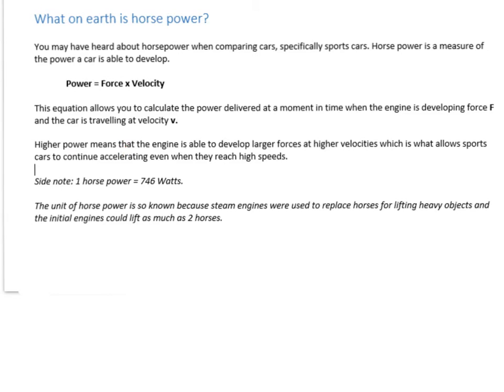So if you have a higher power engine, so you have more horsepower, that means when you're at a higher velocity, you can still develop a large force to accelerate. Even at very high speeds, most cars would have a very low force by that point because they were limited by their power, but if you have large power, then you still have a large force and you can still keep accelerating.